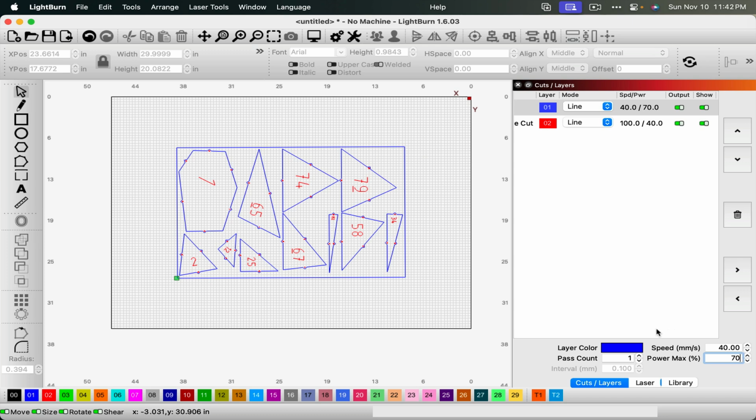So here's your things. Remember the laser cutter process. You want to do the framing, and then lay your cardboard under. Make sure it's flat. Check the depth of the laser head with the little tool, and start cutting and watch it.